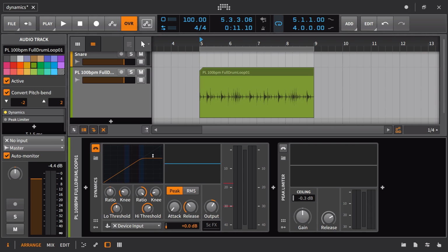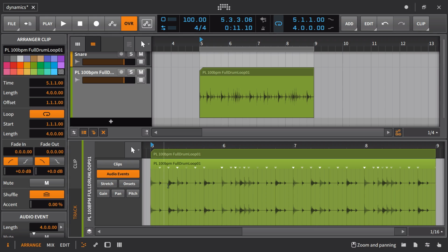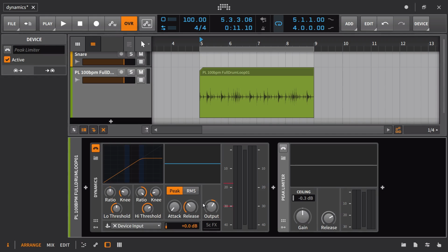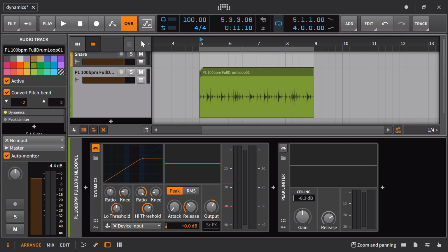So anything that goes over threshold is not going to necessarily output any louder. So we're never going to be distorting. That's really the main idea with limiting. And so what we're doing is anytime we cross the threshold, we're clamping down hard. All right, so we take these peaks, clamp down hard, and then add the makeup gain to compensate. So here's a setting I have with the dynamics. Notice, however, that the attack does not go faster than 0.1 millisecond. That's still ridiculously quick, however, and it's not really going to let too much leakage through.